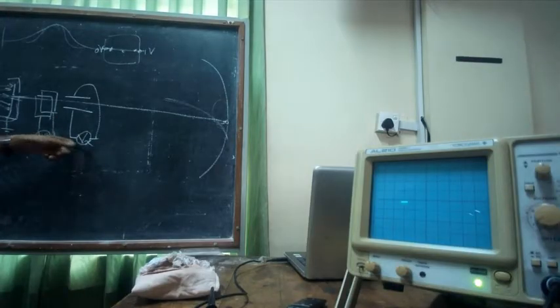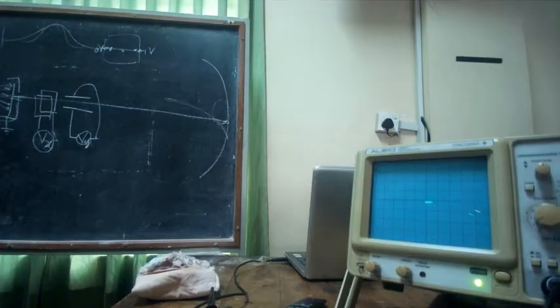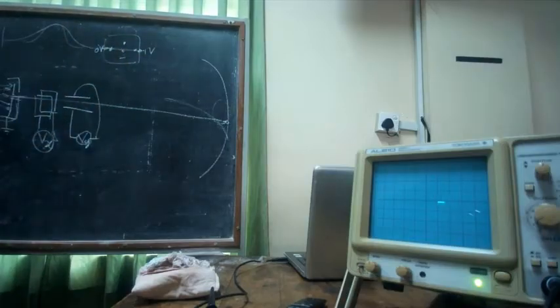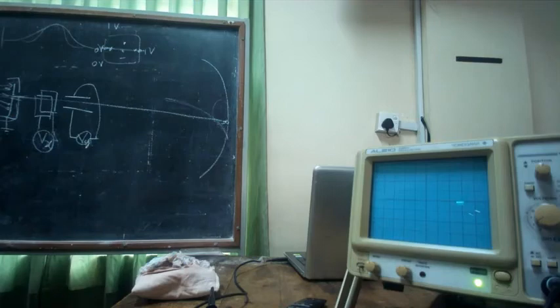By applying this voltage Vy in the y direction, so this is x, this is y, you can deflect it top to bottom, right? So I can focus my beam anywhere on this, but it still will be a dot. Depending on the value of Vx and Vy, this point, again, this may be 0 volts, this may be 1 volt in the y direction, Vy, right? By controlling Vx and Vy, I have a one-to-one mapping on this screen, correct?